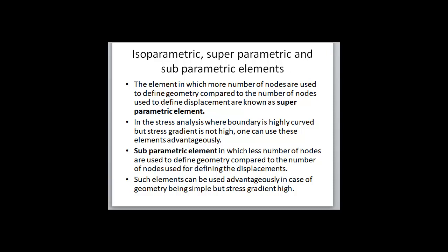Subparametric elements are the ones in which fewer nodes are used to define geometry compared to the number of nodes used for defining the displacements. Such elements can be used in case of geometry being simple but stress gradient is high.